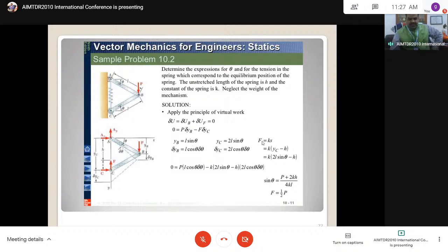And the F is equal to Ks, you substitute K into S. Now we simplify, neglect higher terms. Higher terms are delta theta square, like that. Those terms we can neglect, or throughout divide by delta theta. That is also another way. So now simplify, you will get the sin theta expressions in this form. From this, we can get F is equal to half of the spring force.